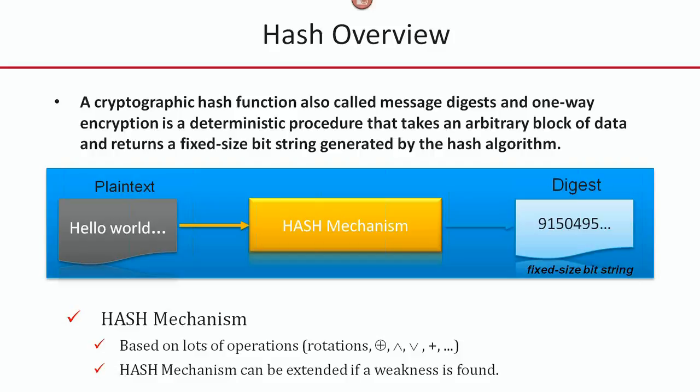So again, if we receive some data, we can calculate its hash, and then we can validate that that is the correct value, that the correct data hasn't been modified or corrupted. So this is very useful if you're building things like bootloaders and you want to validate the image before you program it into your flash memory.